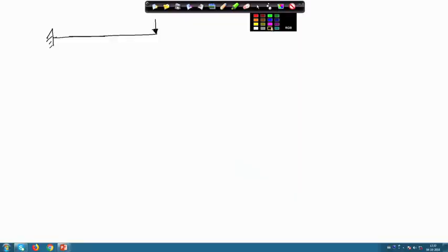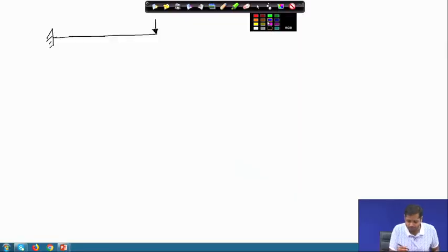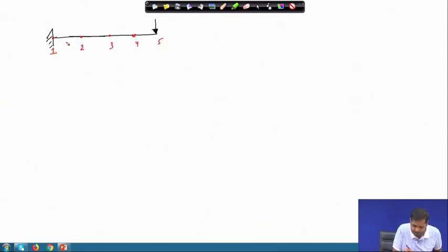So, now similarly first we have to discretize it into several segments. For instance, let us discretize into 4 segments, same as the direct stiffness matrix. We have these node numbers and then corresponding member numbers, right. And then for any representative element we have to construct the stiffness matrix, right.